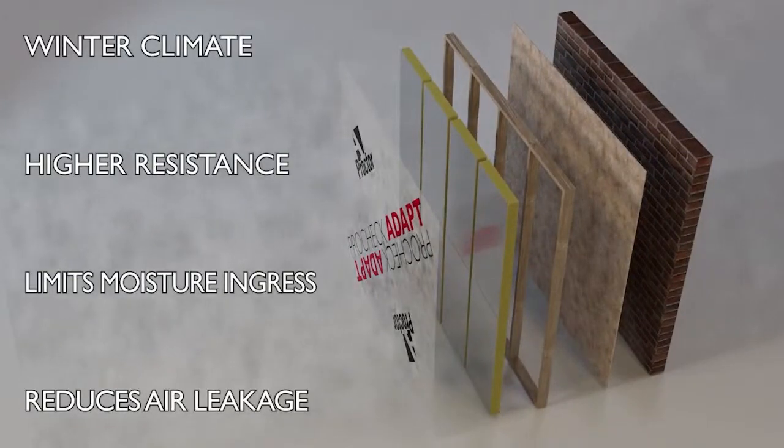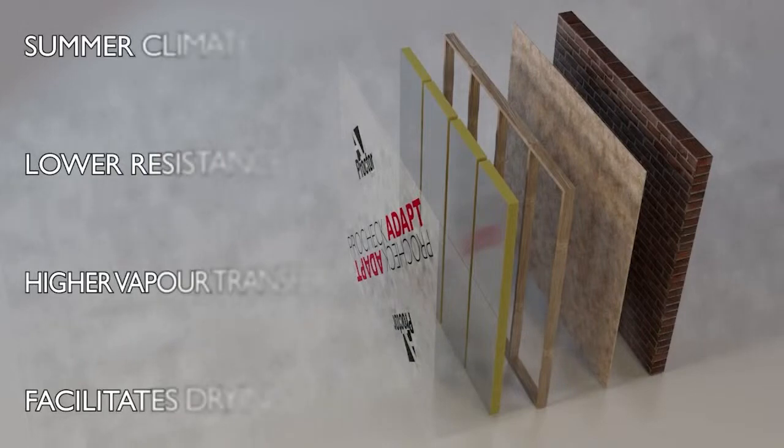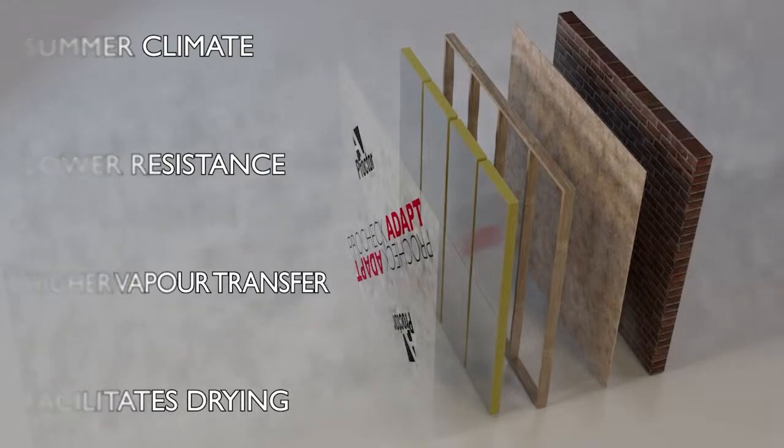In practice, this means the framing can be filled with insulation, then lined internally with the vapor control layer. This limits moisture ingress in the colder winter part of the annual cycle and provides an effective barrier to air leakage out of the heated space. At the same time, over the summer, the higher permeability allows the structure to dry out, removing any moisture that has built up over the colder months.